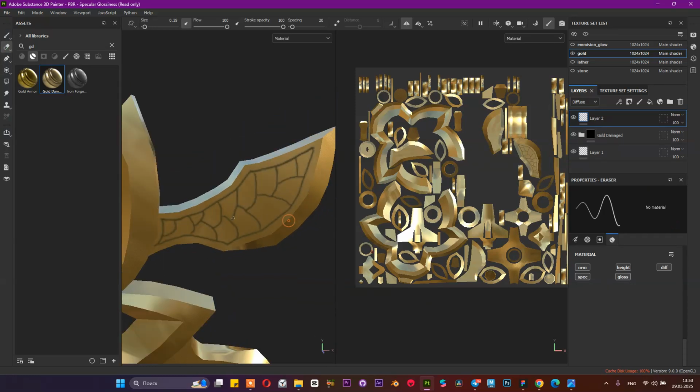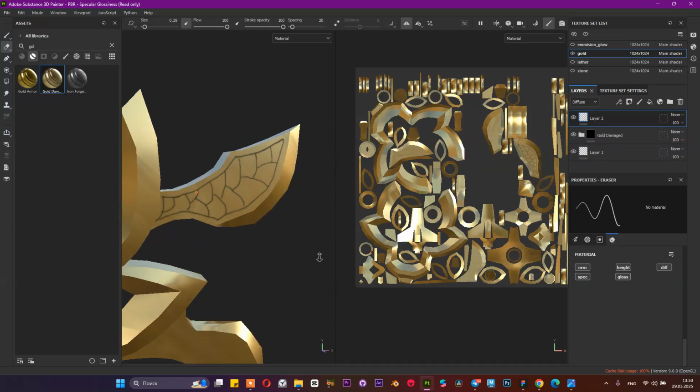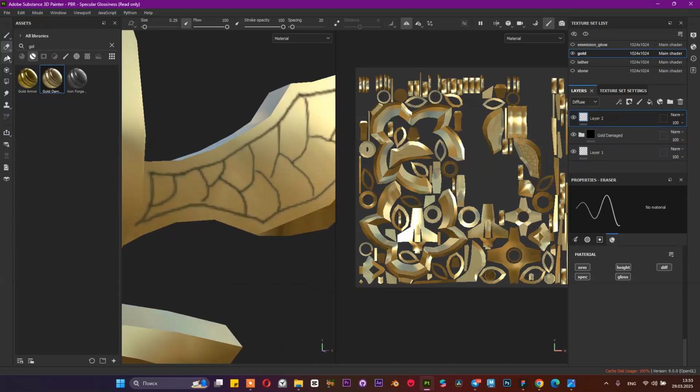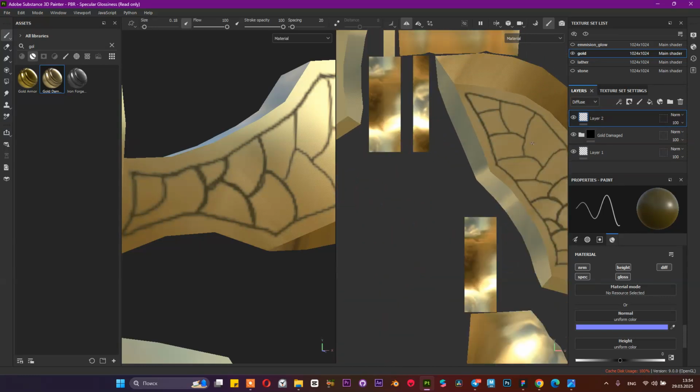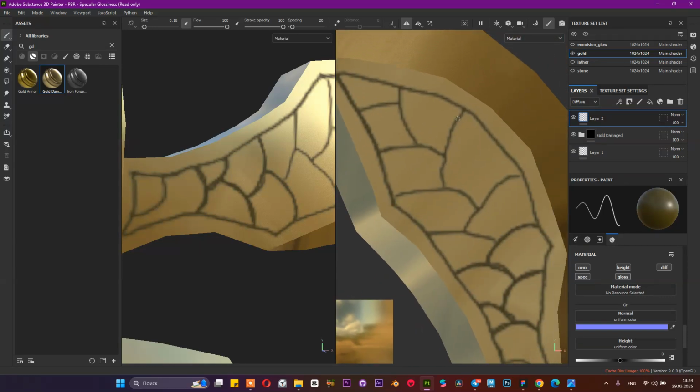The quality of drawing depends on the size of your texture. For example, if you start with 2K textures, your stamp can be less pixelated. If this detail is really small on UVs, it can also have this pixel effect here.